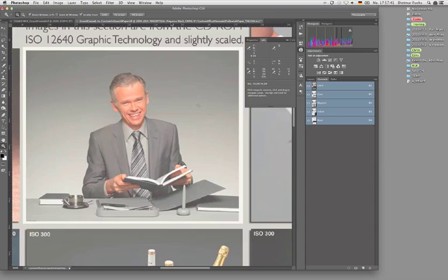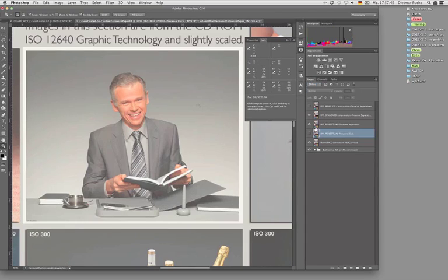So if I switch back here, I now have the other option inside CoPra to choose a rendering option, which we call the absolute compression mode, which will make sure that despite the situation that we are printing on a yellowish paper, I have a neutral background, for example, from this gray background here of this guy. And we can see this here. 0.0, so we have, compared to the original one, neutralized this gray. Obviously, we can't change the paper white. The paper white is yellow, so we are going to print on that paper. But if we put this print side by side to my original one, the gray balance will be much, much closer and a much, much more faithful reproduction of my original.